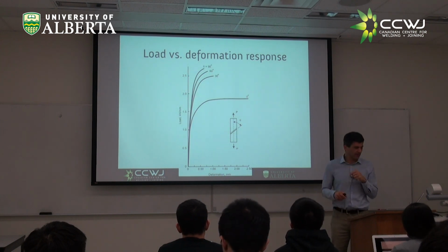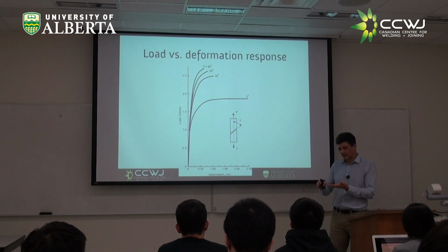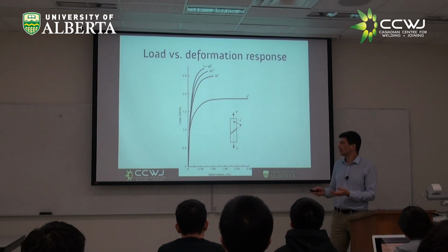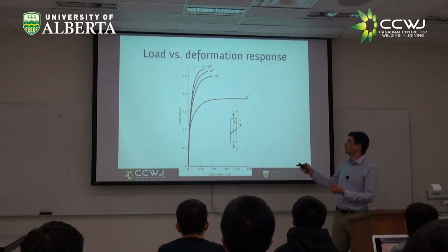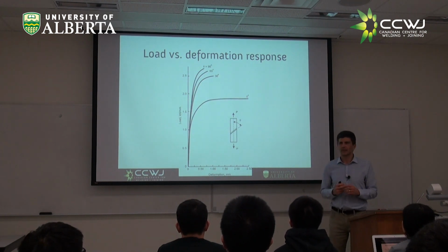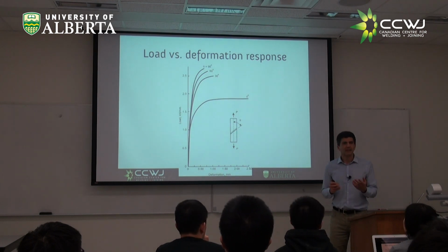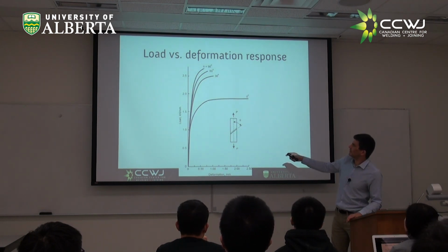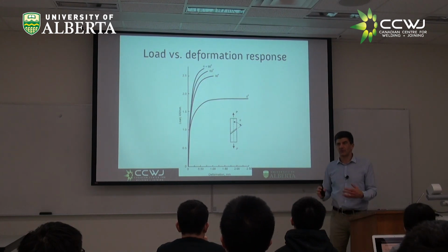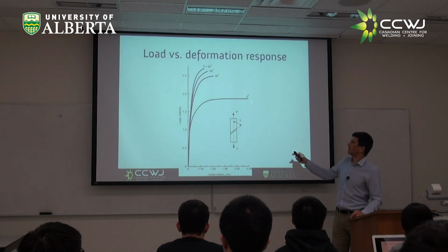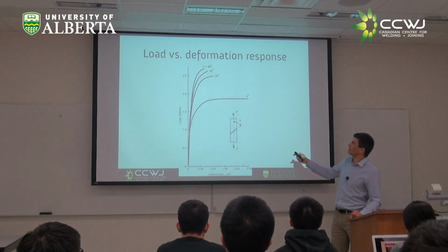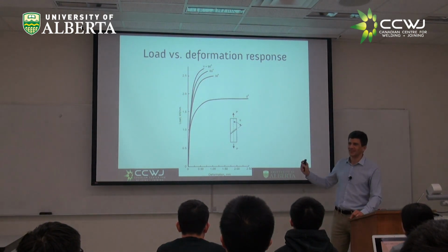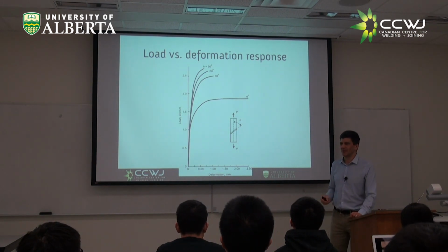If I were to have a weldment that has a combination of longitudinal and transverse, why can't I use the strength of the longitudinal and the strength of the transverse and be happy? Why doesn't it work? Because it doesn't. Why was that? Right, exactly. By the time this fails, this hasn't developed the full strength, right? So, yes, this can eventually develop its full strength, but why would I care about this developing the full strength if I already missed a whole seam, right? Things are going pretty wrong by then, right?